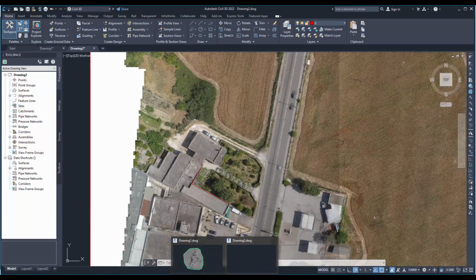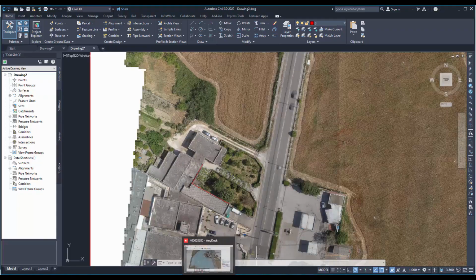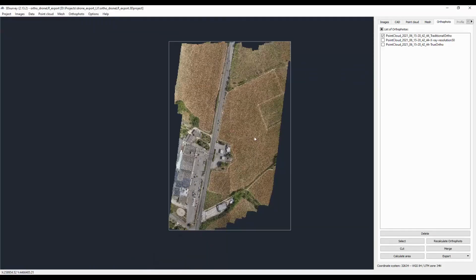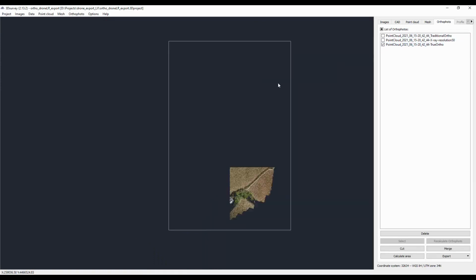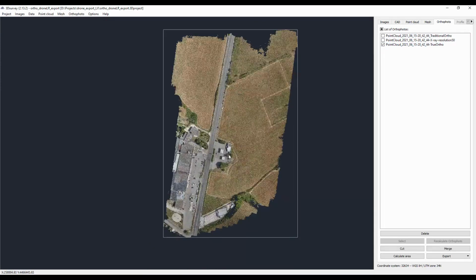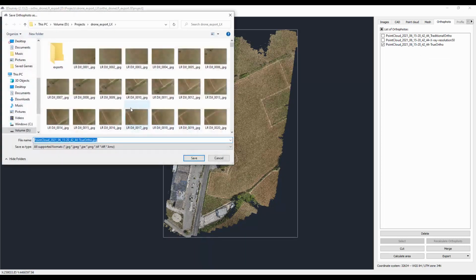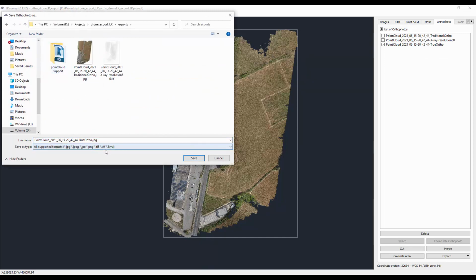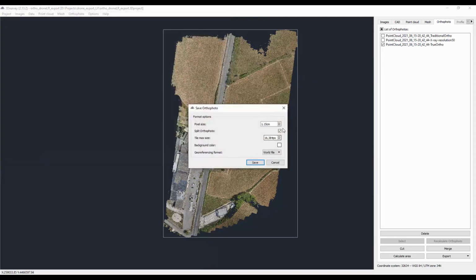let's move back to 3Dsurvey. Here we also have the third option. We also have the true orthophoto. So here, when we will be saving this one, we will choose again the JPEG, but for georeferencing mode we will select the DXF frame.